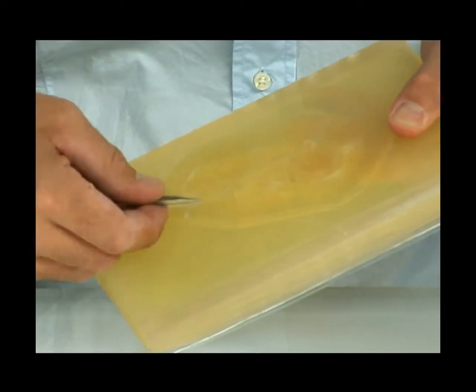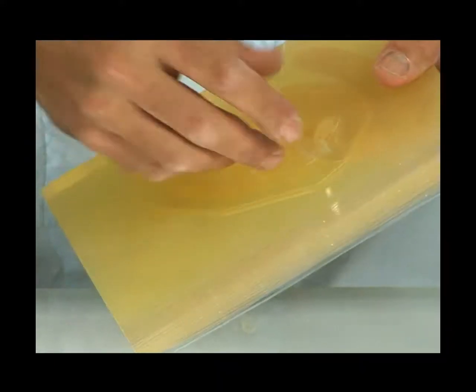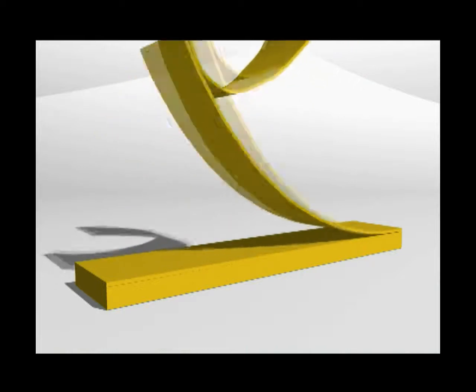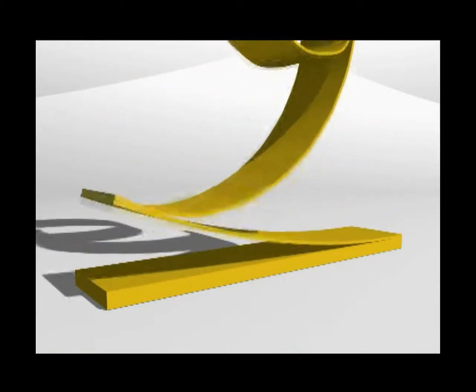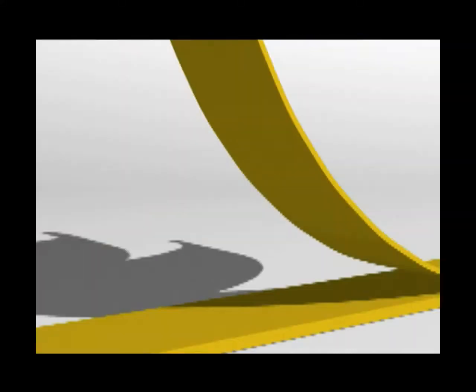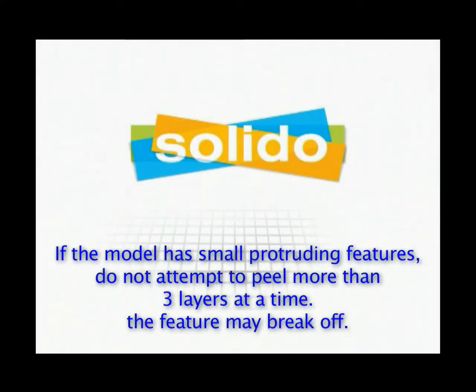As you can see, the layers are attached together in a Z-shaped form. Each layer is glued to the next layer, allowing peeling the entire residue material at once, which makes peeling much easier and faster. If the model has small protruding features, do not attempt to peel more than 3 layers at a time. The feature may break off.